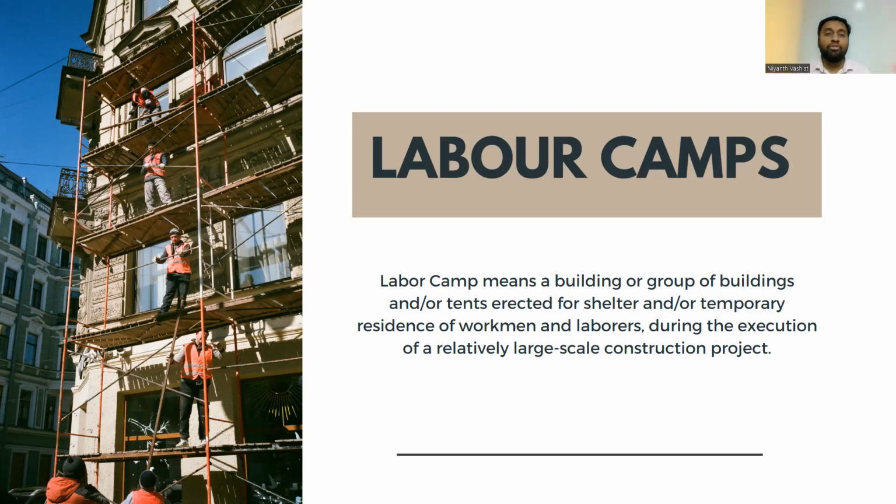Now, if you are working in a site which is directly accessible by public, for example, metro, for example, flyovers, then labor camps are provided inside in a different area. But if you are working in a real estate, township, IT park, or a business park, or a residential block, then labor camps are provided inside because that is a closed space and not every public can enter. That is why it is important to decide where the labor camps are going to come even before the execution work starts.